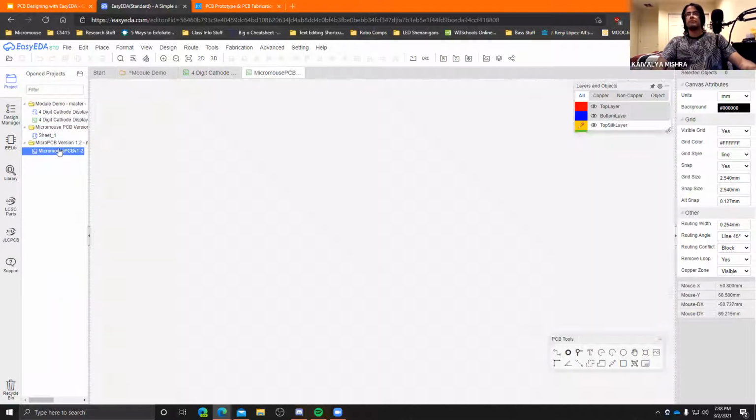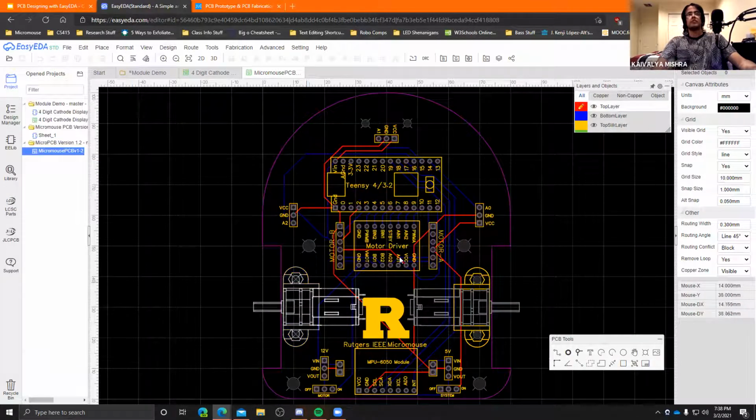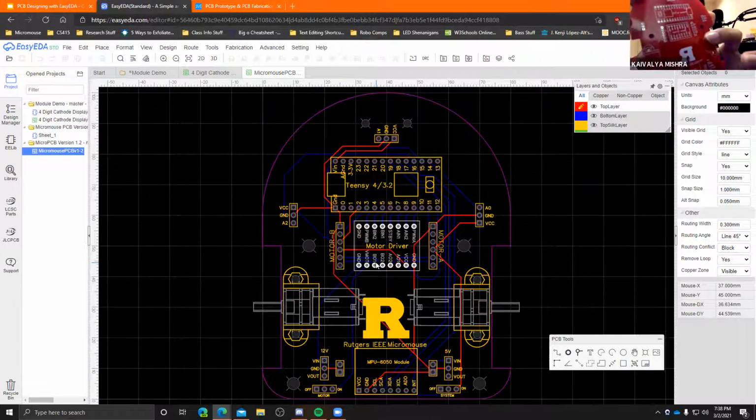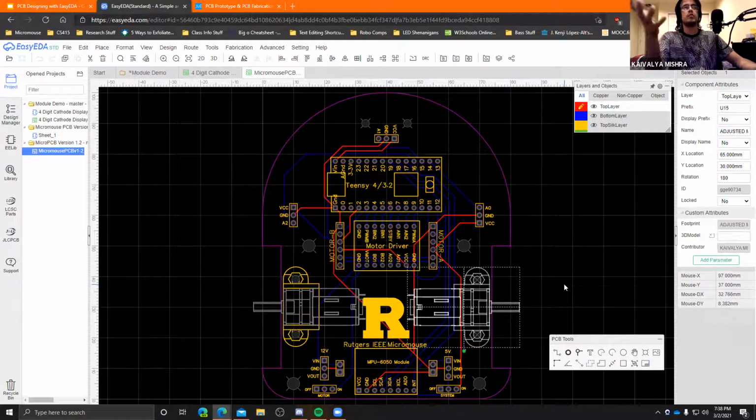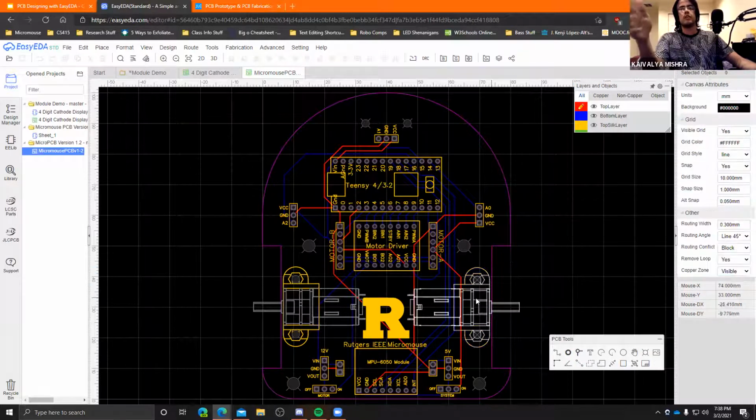Actually, I did use that feature in this board I made right here. As you can see, there's this white footprint for this box thing here, the two holes on the end. That was for the motor housing, and it wasn't really even a component. It didn't connect to anything. It was just to let me know that I can't place my motor driver here, or these pins here. It gives me an idea of how it would turn out. So a footprint is generally good enough.